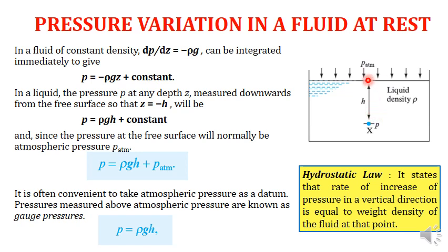So you are moving down, if you consider the surface of the fluid as a datum point. Your point x at which you want to determine the pressure is just below the datum point. For a point below the datum, we consider this height as negative. This negative height cancels out with the negative already present in the equation, and you get rho g h plus a constant.